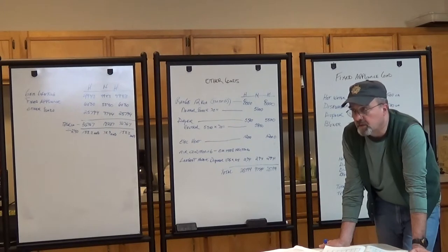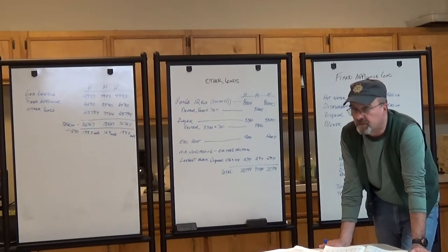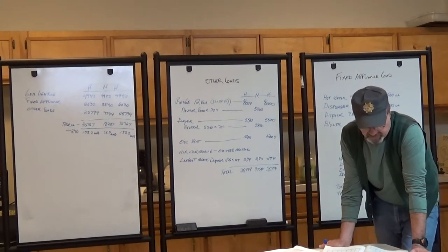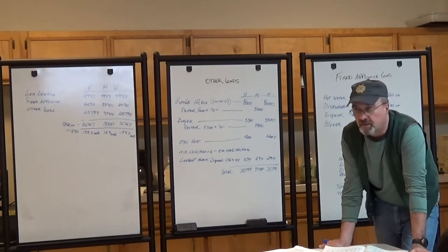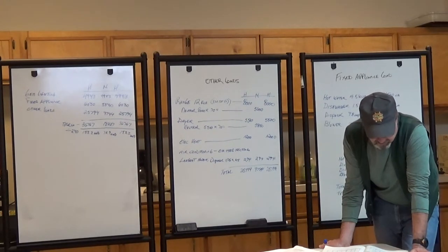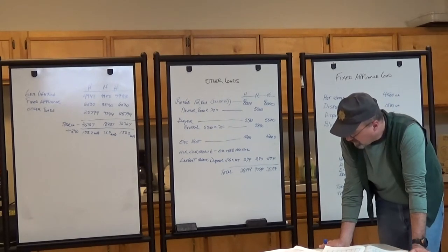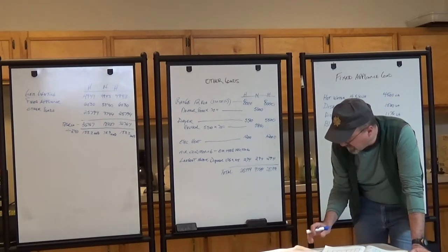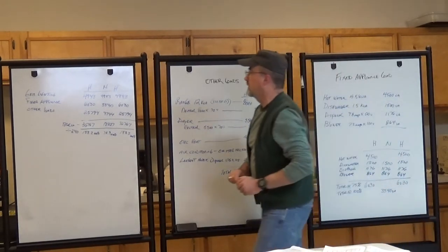We also have to consider what the temperature rating is for your panel board, for your equipment. If it's based on 60 degrees, 75 degrees, or 90 degrees, you have to utilize that column, and then size your conductor accordingly. So that's 170, so that's going to be 1-aught wire.